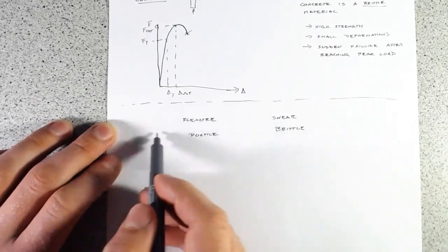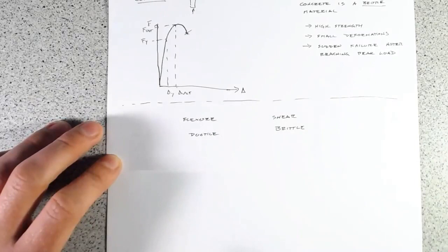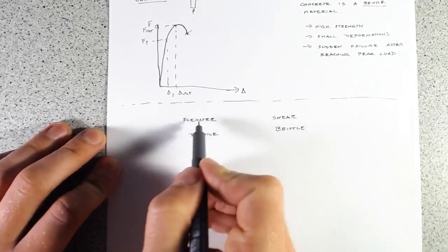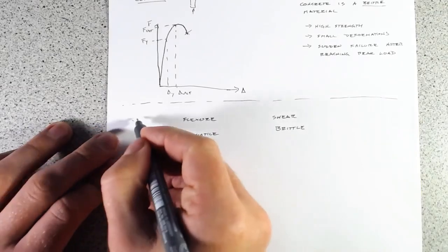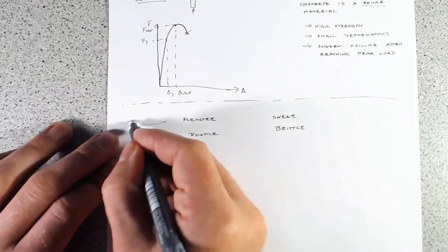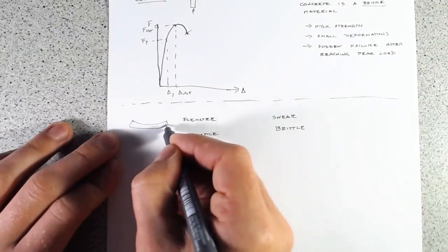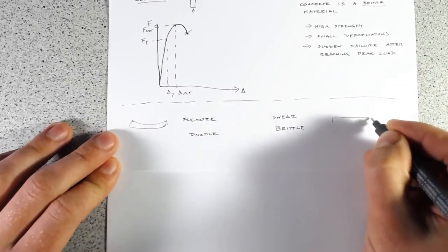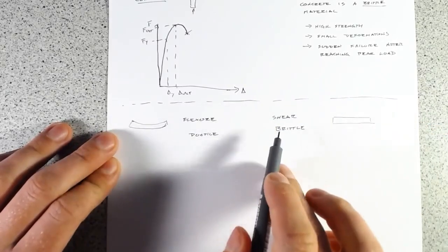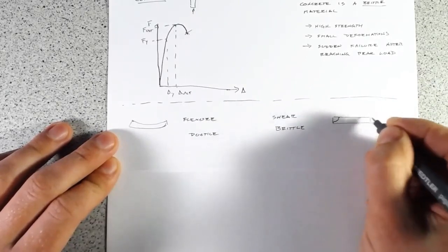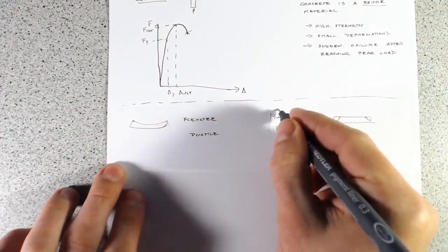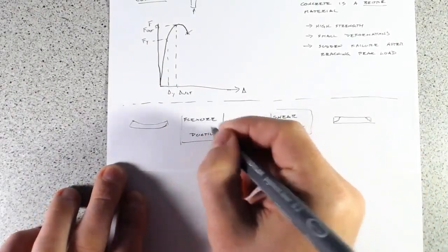We like things bending. If you design your specimen right, you use the right materials and you use them in the right way, you can get beams to bend like literal bananas and still be able to support load. While with shear, because there's not a lot of deformation in shear, we can load, and then all of a sudden the material just lets go. And so shear is a far more brittle behavior than flexure.